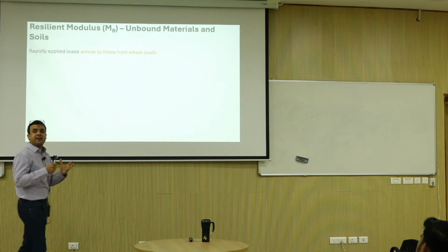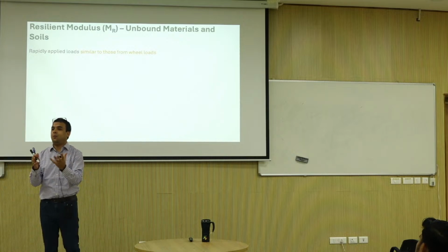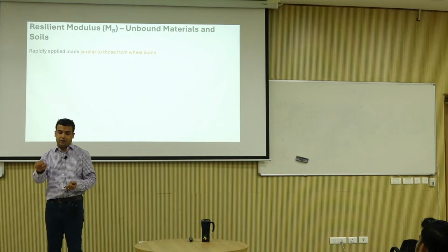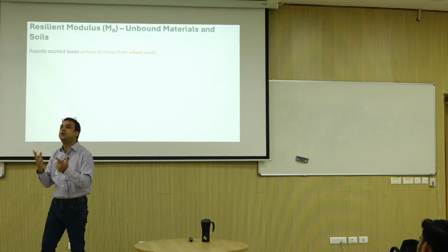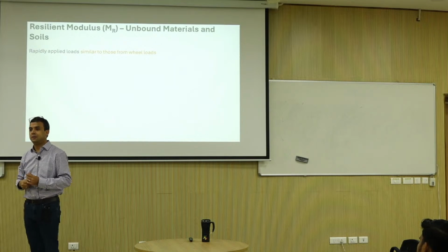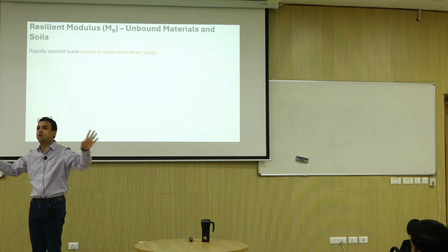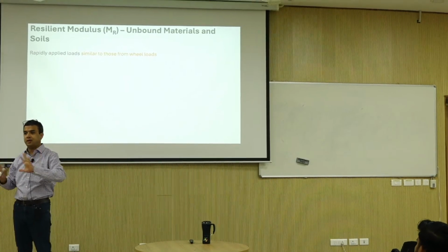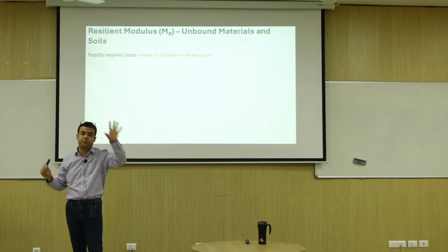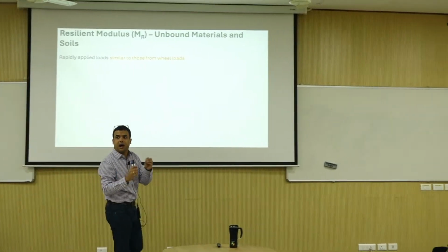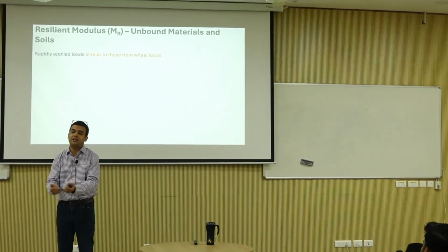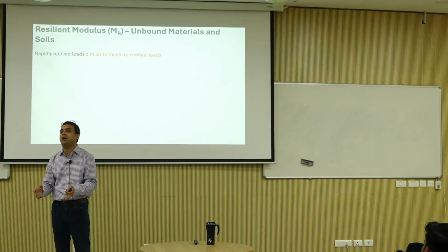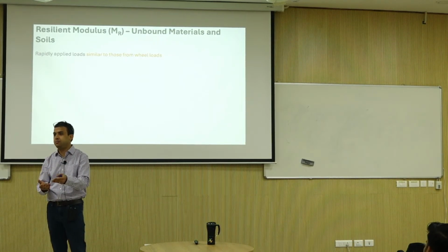I am asking you, tell me what kind of load a soil layer 1 foot below my surface, a soil element, is experiencing on this road, on this national highway. How would you determine it? What would you do? And you have all the resources in your hand. I'm not restraining you. You have everything you need, every equipment, every mathematics. So how would you determine experimentally what kind of stress pulse a soil layer 1 foot below is experiencing?